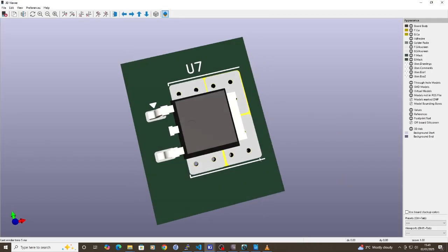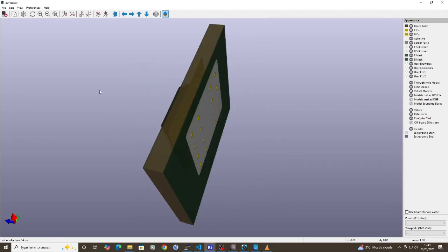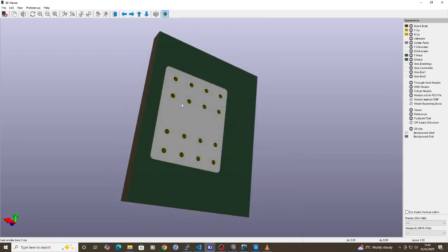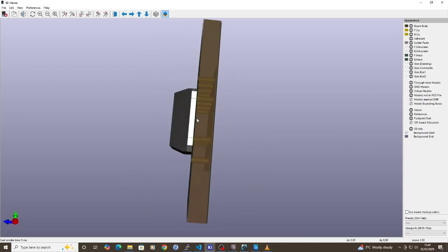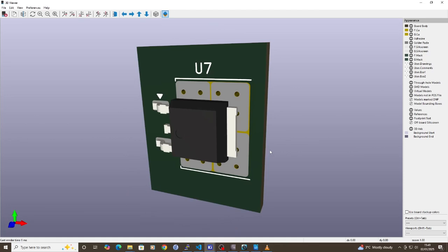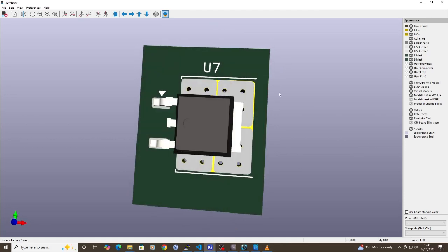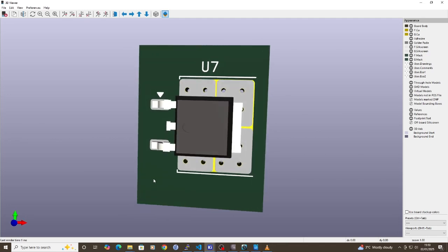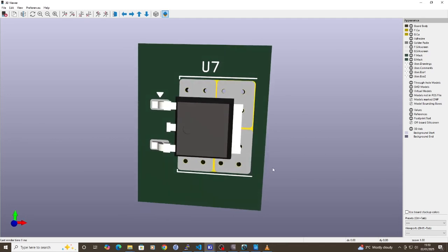We've got an area of front copper and back copper which is not solder masked, and we've got a number of, you can just see them in there, a number of vias connecting the two sides together, and my hope is that this will improve the thermal conductivity between the two layers and help to cool down the 5-volt regulator.